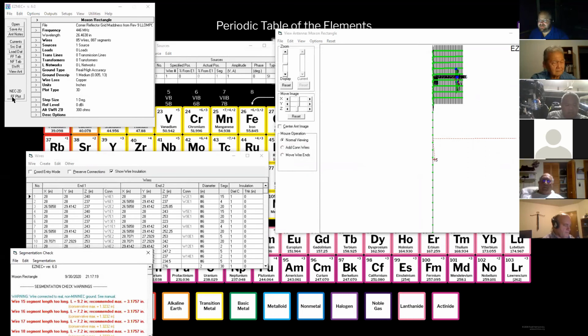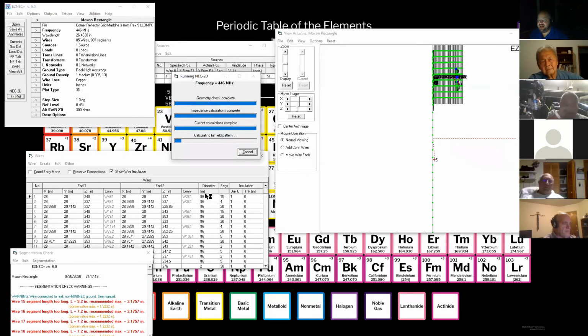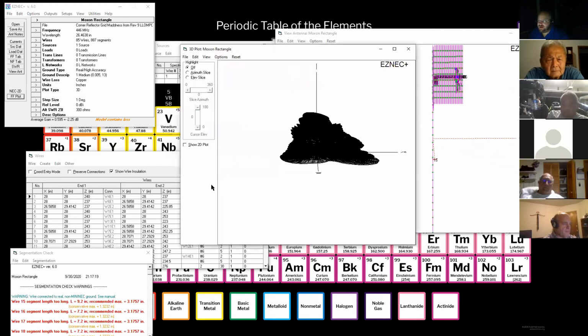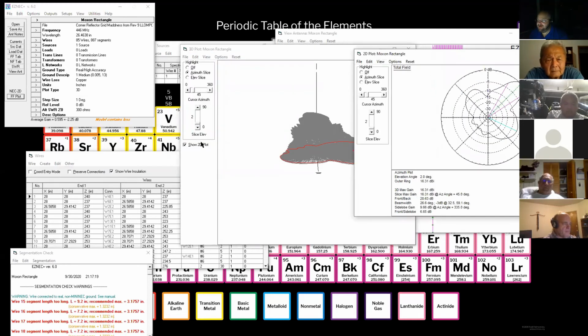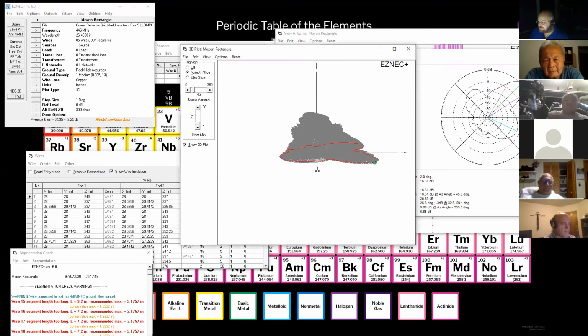So I designed the antenna initially without this because I knew that I needed an antenna that would operate on all 3 bands. It would match up fine on all 3 bands. And then I said, okay, I want to get a lot of gain. How can I do that? And then this is how I ended up with 16 1/3 dB of gain, which, again, take those numbers with a grain of salt. But I found the right distance to maximize that forward lobe. So that's a way that that can be done.